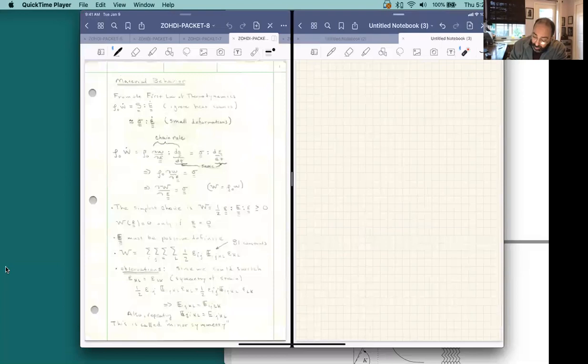So here is our basic issue. Whenever we pull on a piece of material, for example, a thin sample, usually it is given something that looks like this. It usually has some grips on each of these sides. I'm just going to show it as a gripper. The gripper is going to pull the material in different directions. And then we're going to have some kind of a strain gauge that is essentially going to read out pieces of information as the area here starts to deform and change.